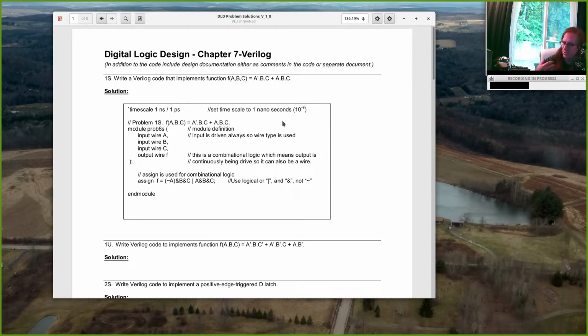And so we started talking just very, very briefly about Verilog on Monday. It's this design language we can use to describe circuits, and then we can use software to take in those descriptions of circuits and either actually configure a physical piece of circuitry to implement our design, or for us, do a simulation of the circuit we're describing.